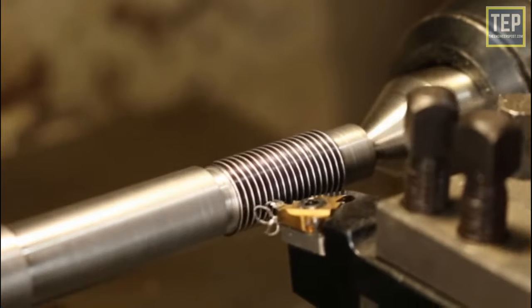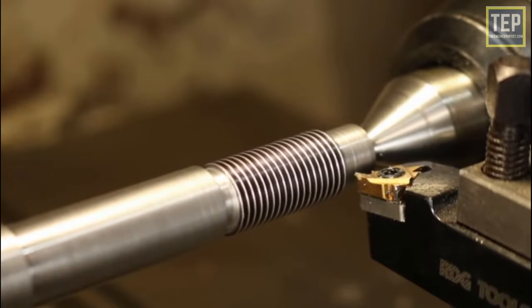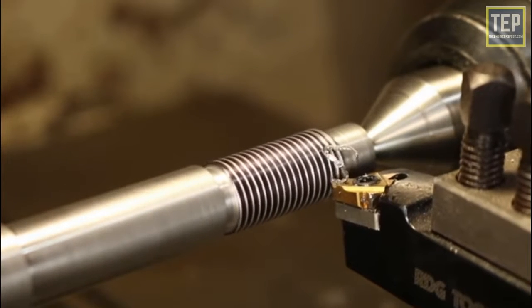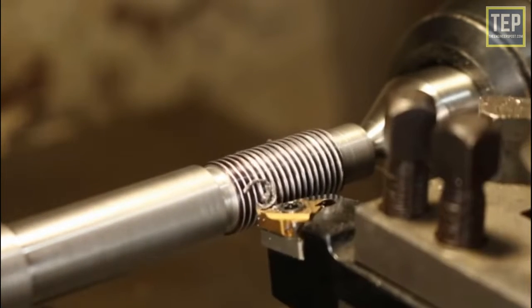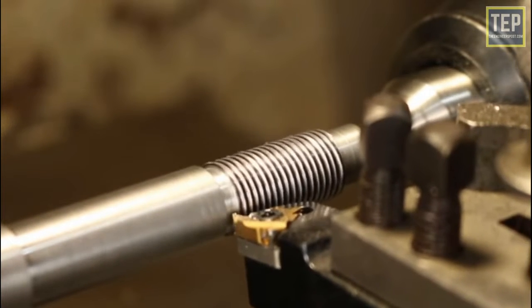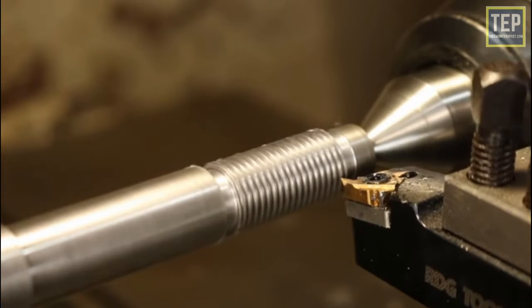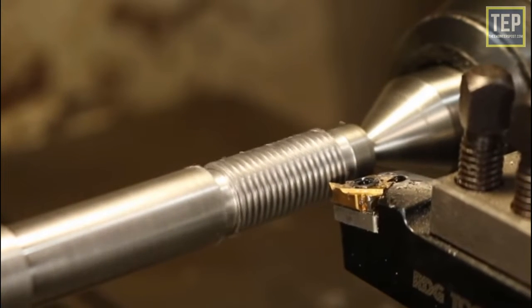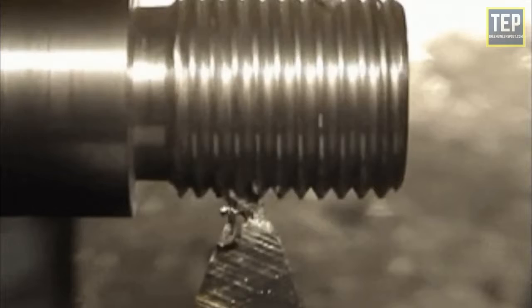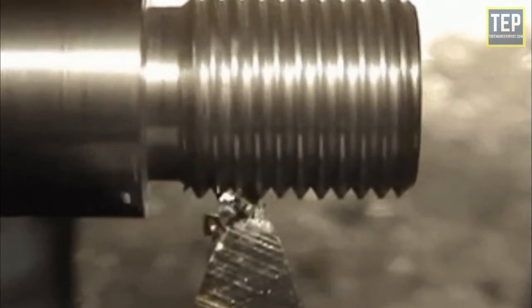Thread cutting tool. Metric, BSW, or American V-threads are formed by a single-point thread cutting tool. Its cutting edges are sharpened to the shape and size of the thread that is to be cut. The size or cross-section of the cutting edges of the tool depends upon the pitch of the thread. So for machining different screw threads having different pitches, separate tools are used to produce accurate threads. The nose of the tool is pointed, flat, or rounded according to the shape of the root of the thread. A thread tool gauge is used to check the shape and size of the tool after it has been ground.